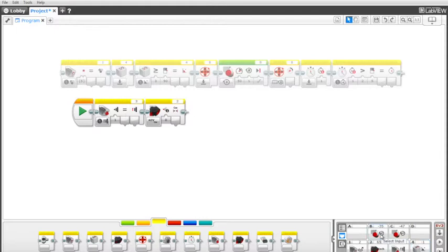Now let's look at the motor rotations. Let's look at motor B. You can measure the motor rotation in degrees or in number of rotations, or if it's running, you can measure the power. For example, if we measure the rotation, before you make use of the measurement, you always want to reset to 0. So you just click at the port, and then it will be reset to 0.